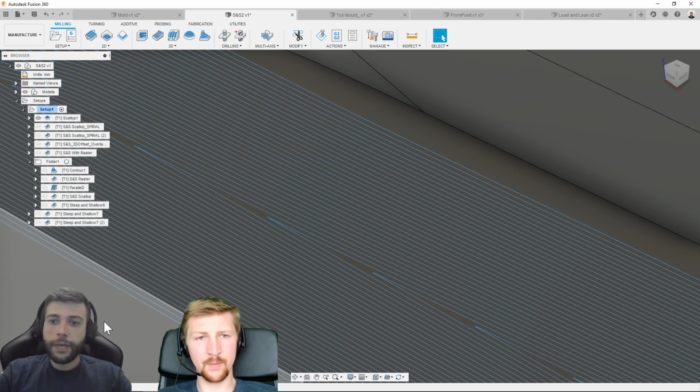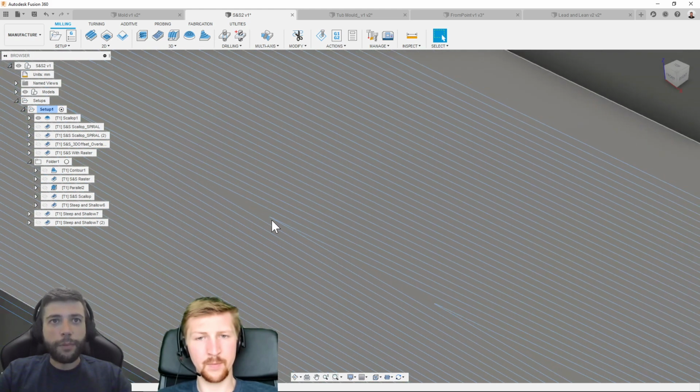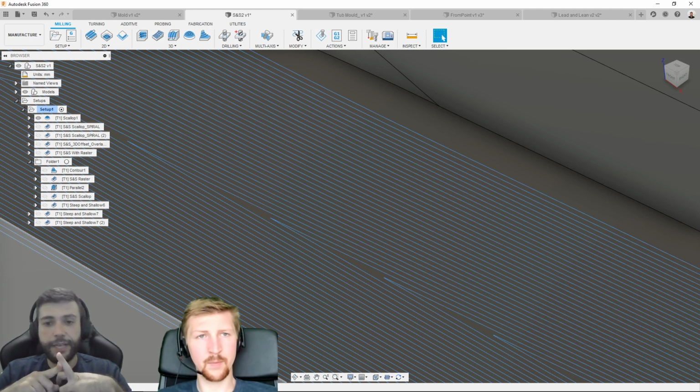Now again, we do have a way to deal with these sharp corners, which are detrimental. They're obviously a problem. They're a problem for surface finishing. They're a problem for the tool life. Obviously, such a sharp change in direction for your tool may mean extra engagement. And it can be a problem for the machine itself because it's got to change direction that sharply whilst it accelerates.